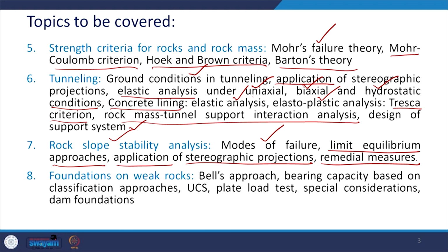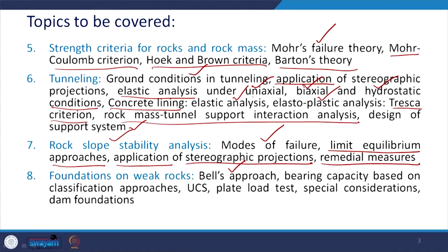And finally, we will discuss the foundations on weak rocks. You all know that in case of soil, you have Terzaghi's bearing capacity theory, but that does not work in case of rocks. So, we will learn about Bell's approach. Then the bearing capacity based on various classification approaches which we have seen, RMR, Q, etc., then systems based on UCS, based on plate load test results, and some special considerations and aspects related to dam foundations that we will be discussing.